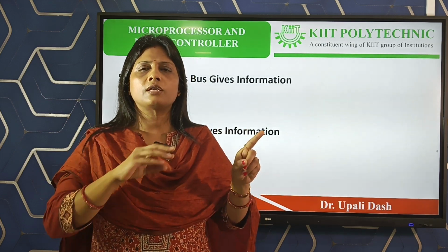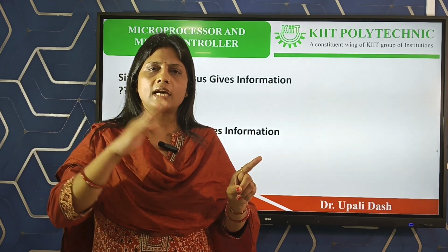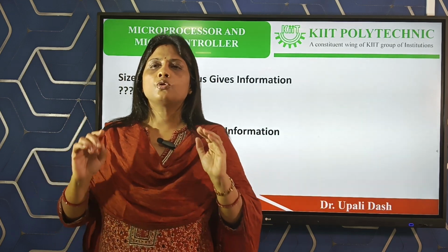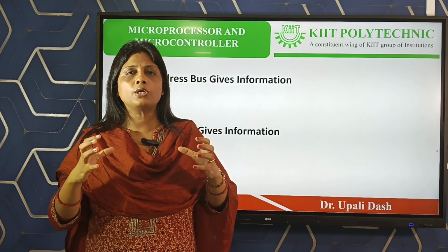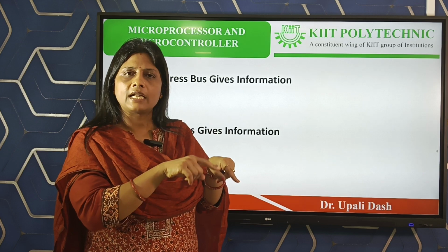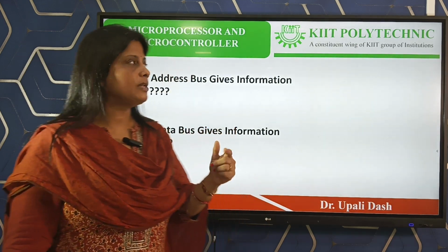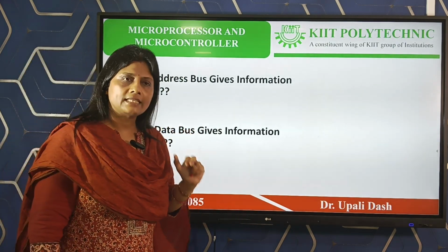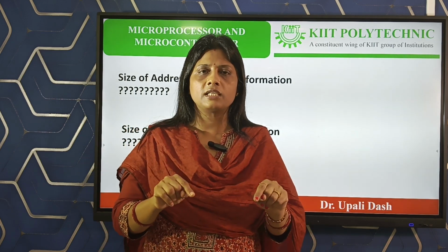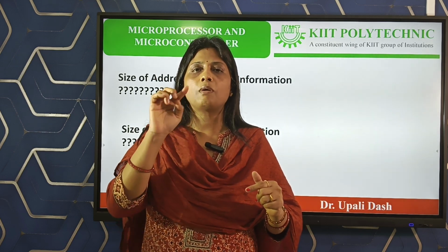If a processor has to process any data, then it always has to interact with the memory. From memory, it should take data. To the memory, it should send the output or processed data. So what size of memory is really fitting to the processor? If I am a processor, then what kind of memory is compatible with me, that I should know, and that idea is given by the size of the address bus. So for example, Intel 8085 is an 8-bit processor having a 16-bit wide address bus, so the memory that we should buy for it is 64 KB, that is 2 to the power 16.